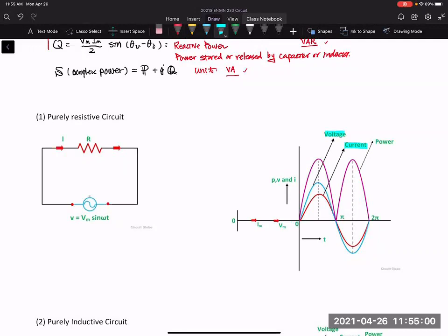If the impedance is a real number, you are not going to induce any phase difference, because a real number has a phase angle equal to 0. So the voltage and the current have the same phase. If we represent the impedance as Z sub R, since it is a real number, we can represent it as R with a 0 degree angle.